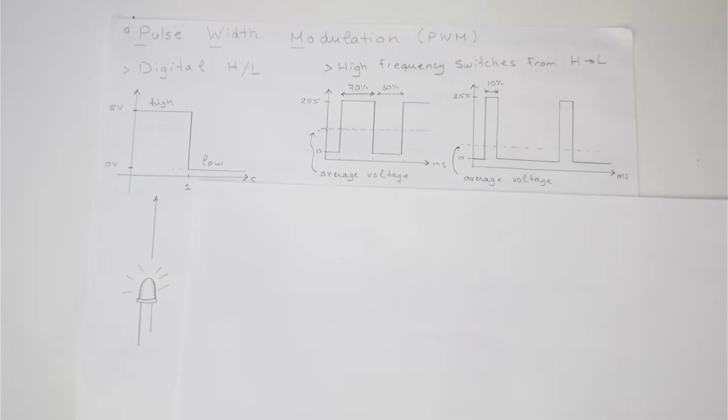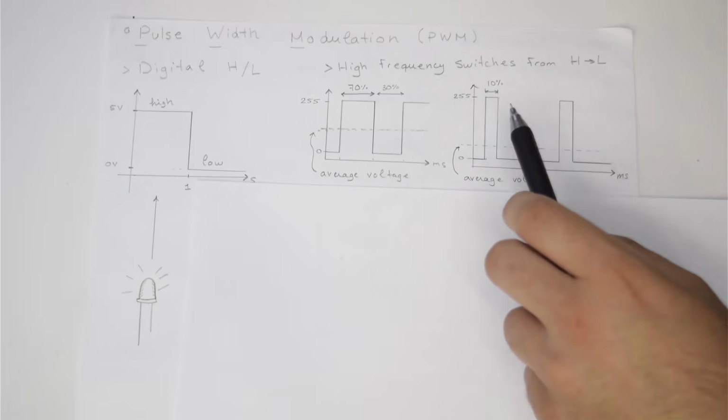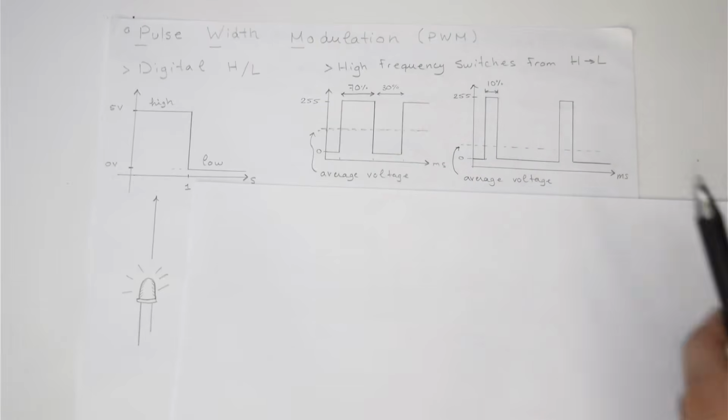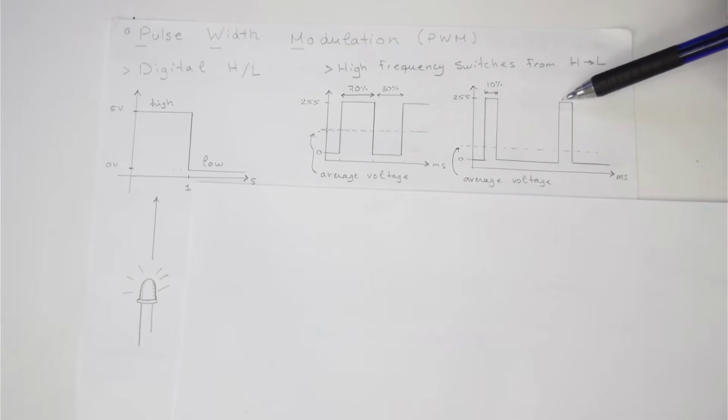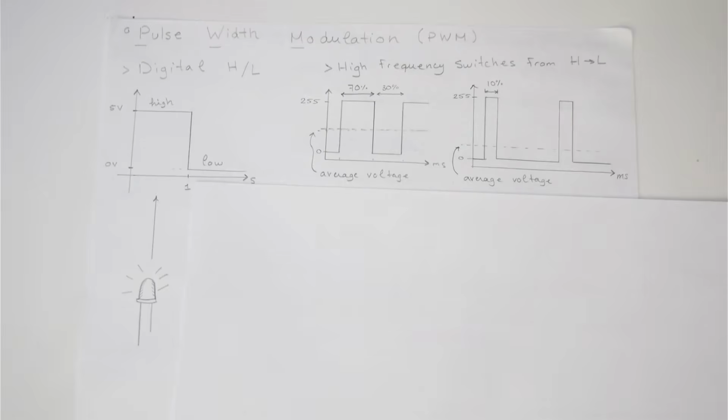All right. The switching frequency is 1 over the period, which is from any peak to peak. So from here to here is one period, and 1 over that is your switching frequency. We control the amount of power delivered to a device, and so we control the behavior of the device. Okay, so that's how that works. Now on the Arduino, we have different timers which can have different behaviors, which I'll get into later.